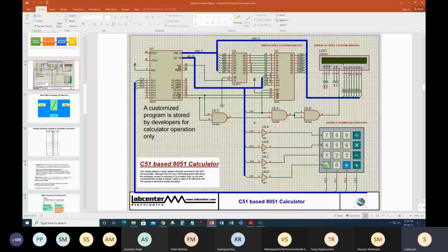So enable E is the enable module, similar to a chip select or chip enable kind of signal, but the name is different for different modules. You have to make sure that whenever the RAM chip is enabled, the LCD is disabled on the data lines. So the data lines for the LCD must be disabled. That is possible through the read, write, enable and register select. There is an RS signal. We'll see that later on.